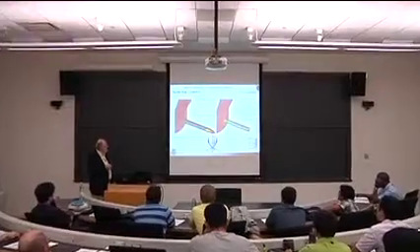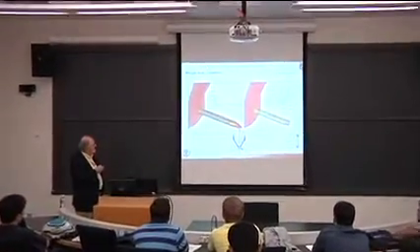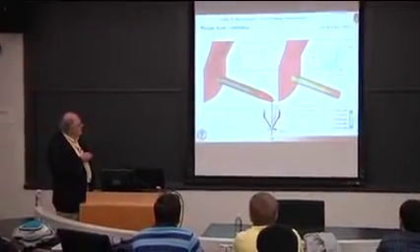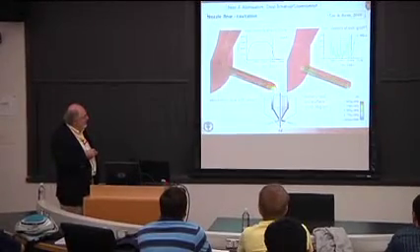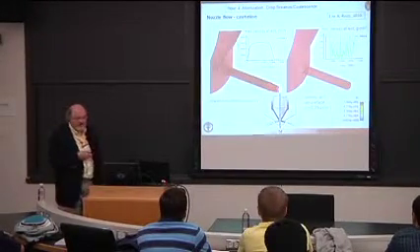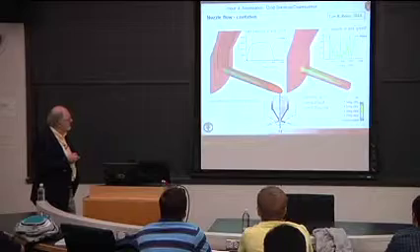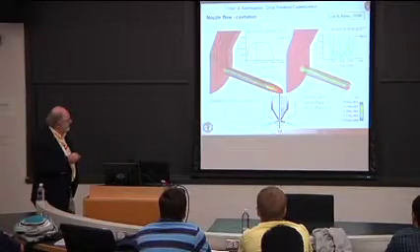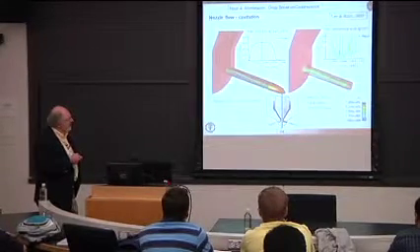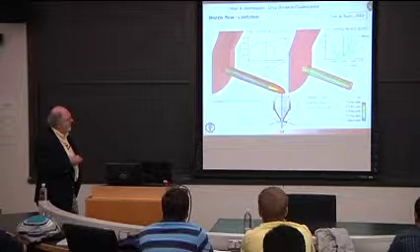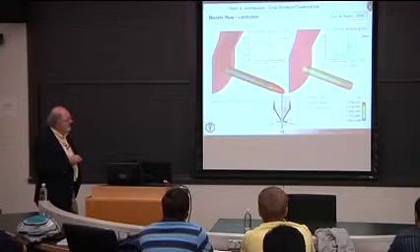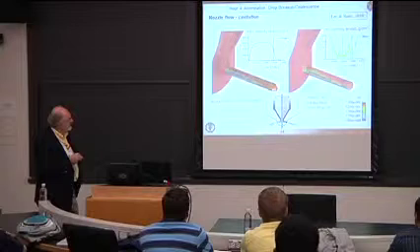So this just shows an example where we did a calculation looking at one of the holes of a multi-hole nozzle here. If you look carefully, you can see the needle over here is moving with time. And what I'm plotting here is the flow density inside the nozzle passage, or inside the flow domain, together with the streamlines. And over here is the velocity, the average velocity across the cross-section at the exit of the nozzle.